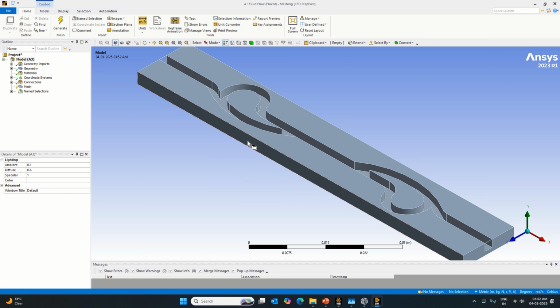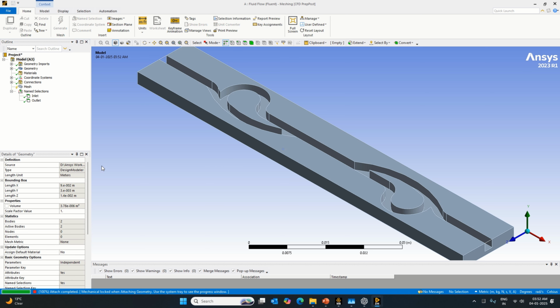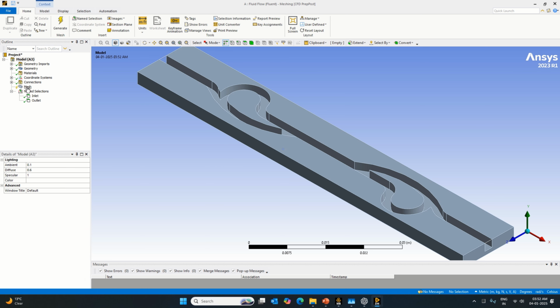So okay, not an issue. So just click on generate mesh. Now the thing is, whatever element size we have selected earlier may be very fine for this case, because we are also considering the solid part as well as the fluid part, and that's why you might have to reduce the element size whatever it was present earlier.